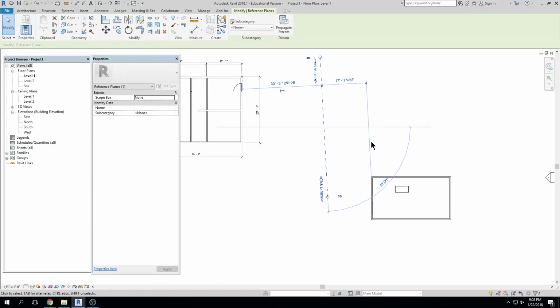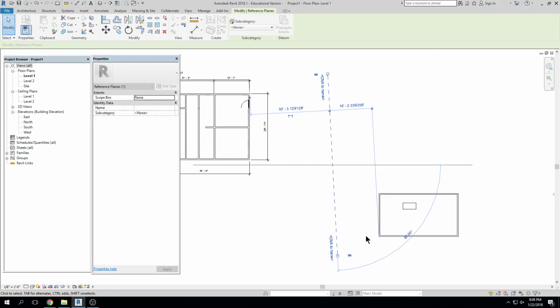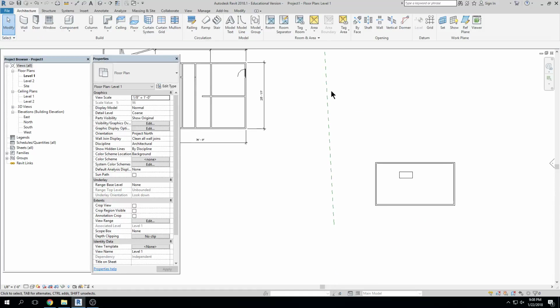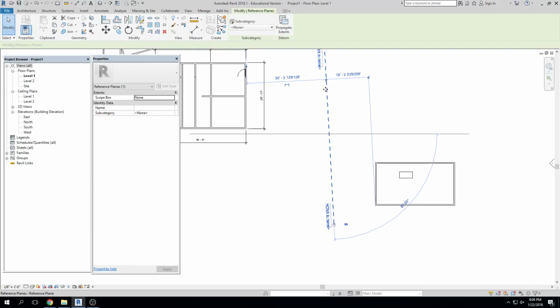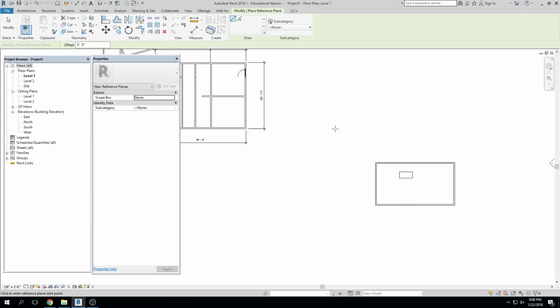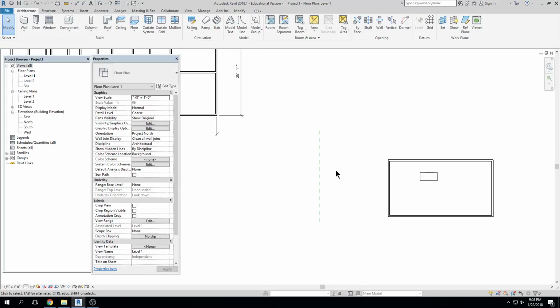I click on it. I can grab the end and drag it out. I can give it a name to remember it by if I want to. Okay, I can align to it. I can extend to it. I can copy these. I can rotate them. I can delete them if they're not what I wanted, which that was crooked. RP, click, click. Okay, AL, align, click, click.